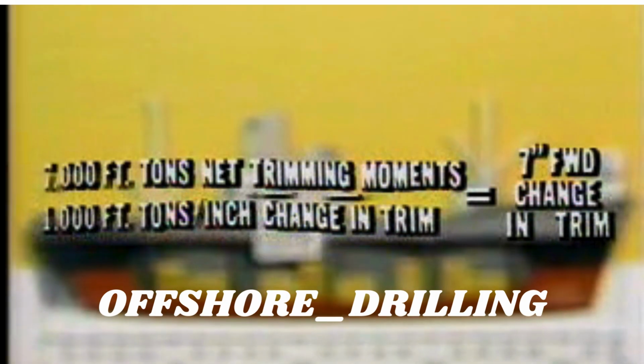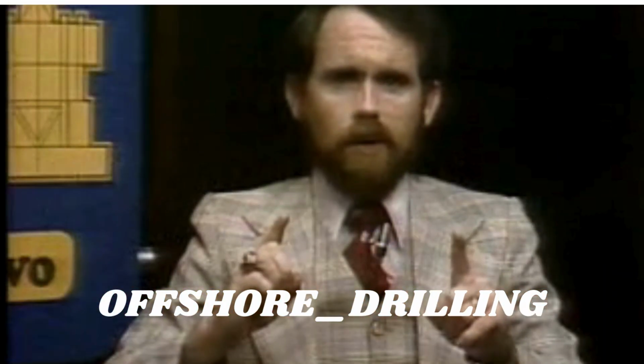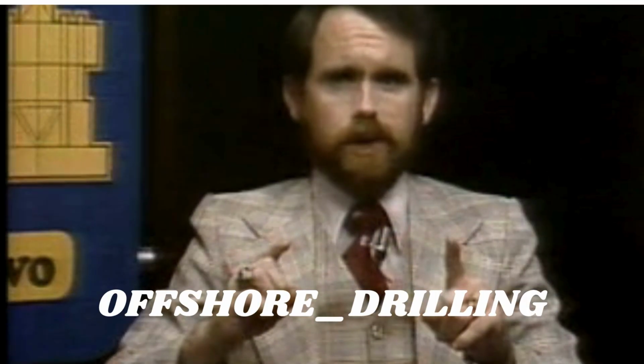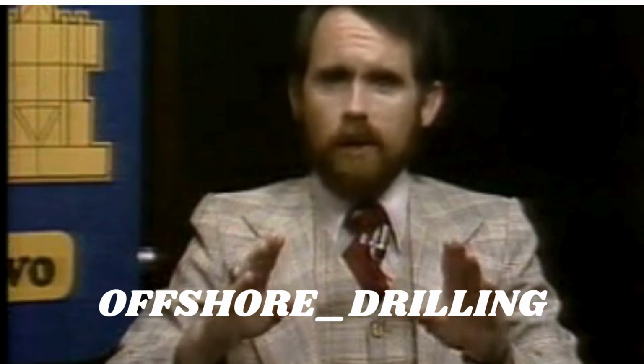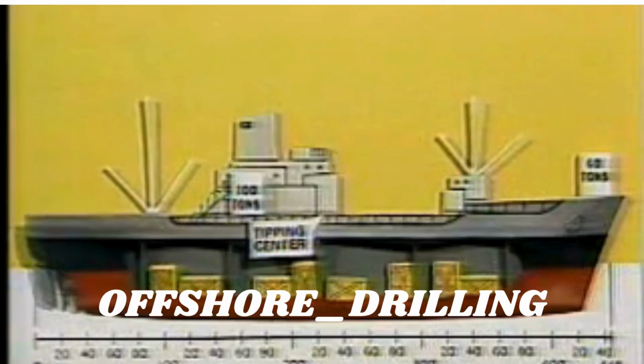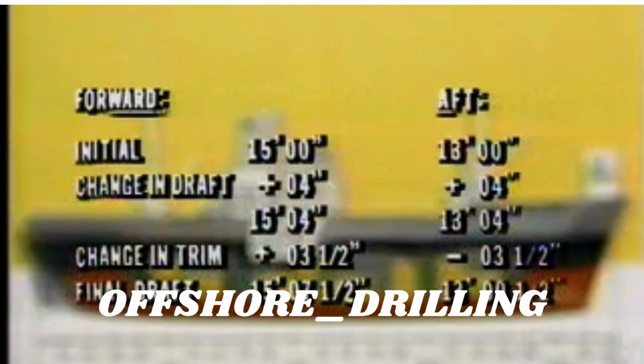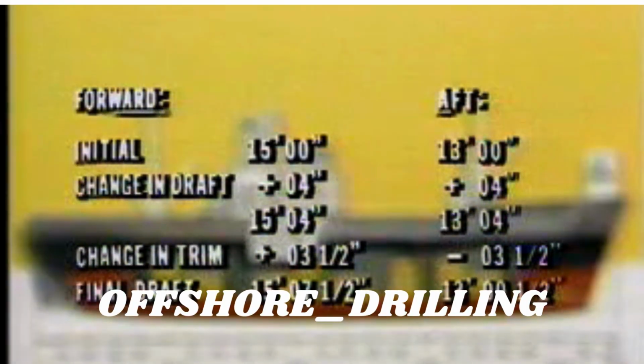Final change of trim of 7 inches by the head. Note that this is a change of trim from the original trim. So what are the final drafts and the final trim? The initial forward draft was 15 feet. This was increased 4 inches by loading cargo to 15 feet 4 inches.